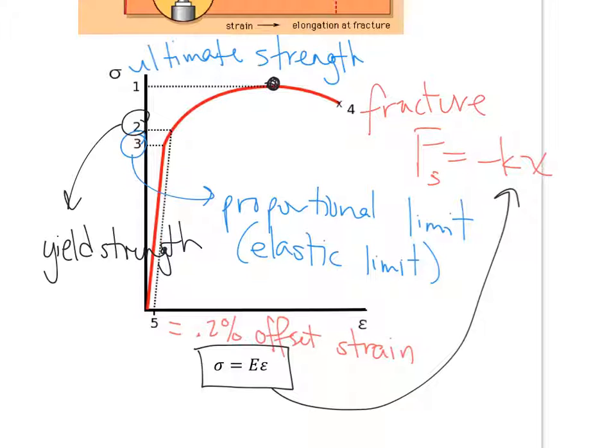I think that's it for this. I'm just trying to jump ahead if there's anything else. So this is what they end up coming out with. Take a look. The maximum stress that it could withstand, the yield stress that it withstands, so right up to here. At this point, it's many pounds per square inch, PSI. At this location, that's when it starts to become plastic deformation, and it reaches this much at a max, and then starts to dip back down. They didn't show the dipping back down part. It elongated by 35%. It's pretty incredible to think about that. That stretched an additional third of its original length.